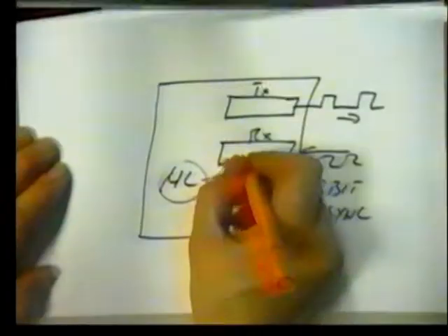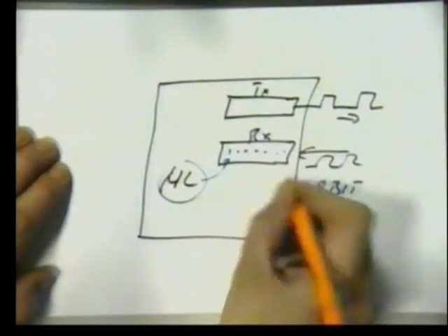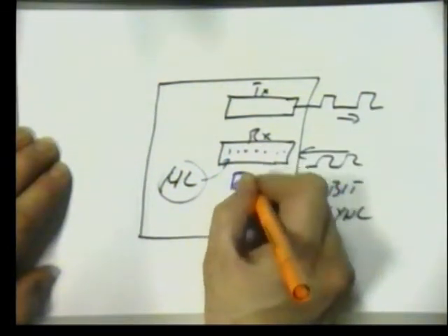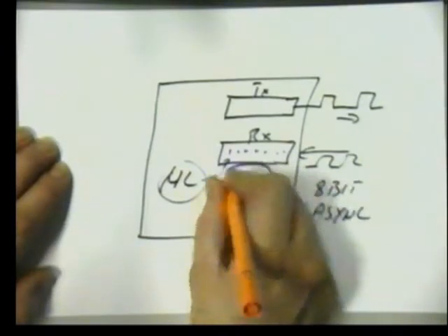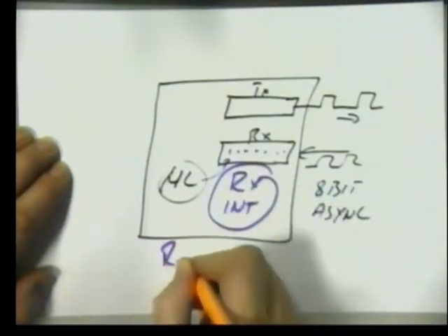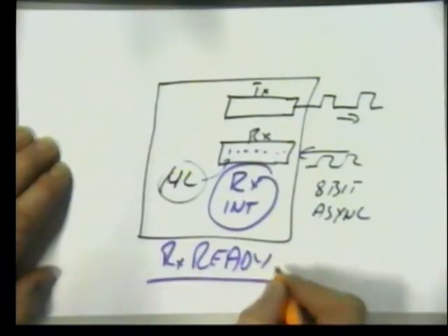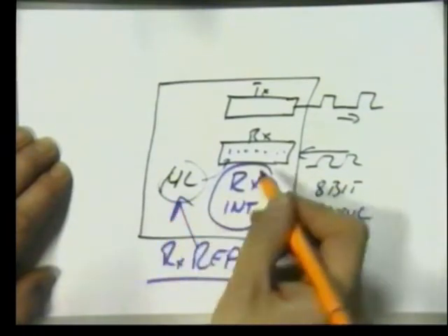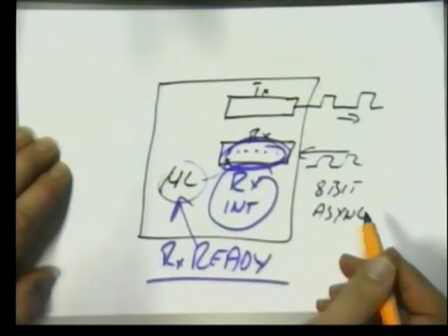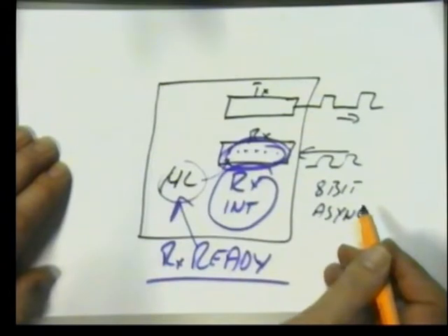So we have associated with this that when 8 bits have occurred, we issue a receiver ready interrupt. And that issues a call to the processor to say, oi, stop! There's something in the receiver, grab it now, read what it is, it might be important.